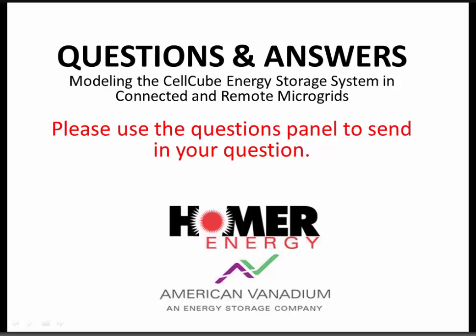long lifetime is that we're dealing with the vanadium element. And in most energy storage systems, you have two dissimilar elements. So each time that you charge and discharge, you get some sort of chemical change of state happening, and that normally leaves some sort of residue behind each time that happens, and it's that residue that tends to build up over time, which tends to kill a battery.